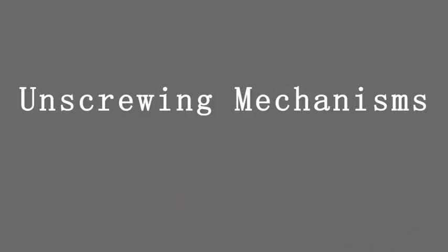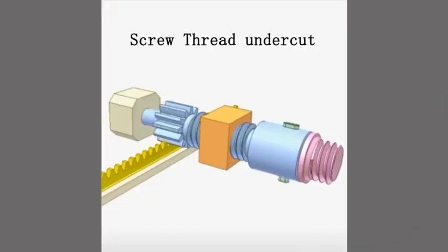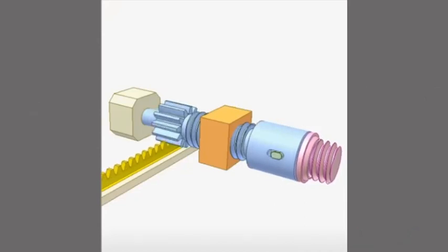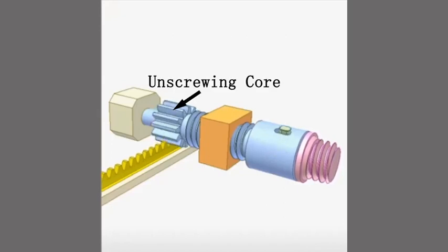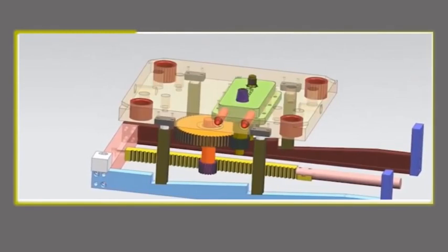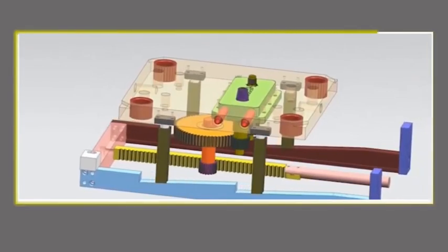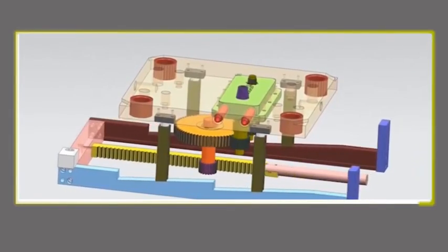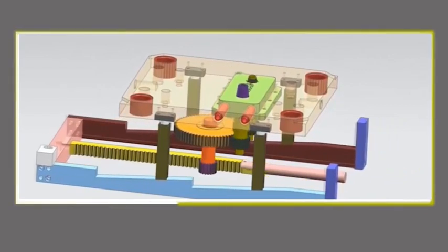Screw threads in an injection molded part create undercuts. To address this, a turning core is needed. The turning action is either powered by the mold opening action or a hydraulic cylinder. When opening the mold, before the opening action, the hydraulic cylinder drives through a series of gears, rotates, unscrews, and extracts the turning core, so that the screw thread is not stripped by the mold opening action.